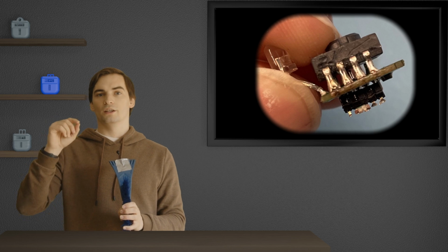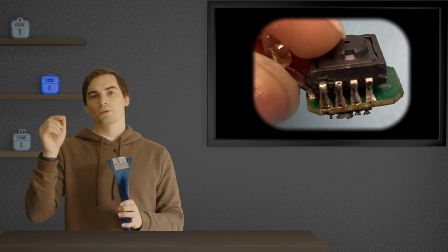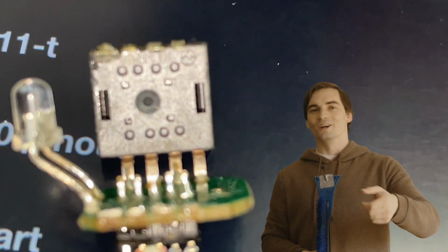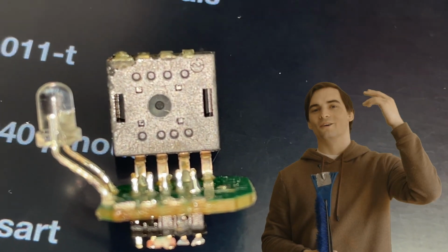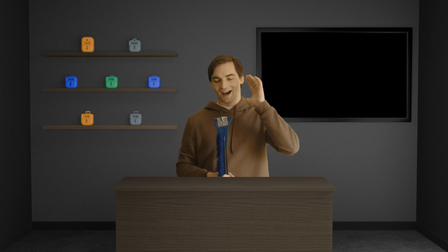So now we know how it works, but how do we talk to it? Well, I can find a datasheet off of this and make sure the model number is correct this time, just as we did before. But the problem is that the model number is written underneath the photosensor and the PCB is in the way. And I'm not proud of this, but the solution that I ended up finding, basically, I cut the legs off, I folded it over, I took a picture, I folded it back over, and I soldered all the legs on.